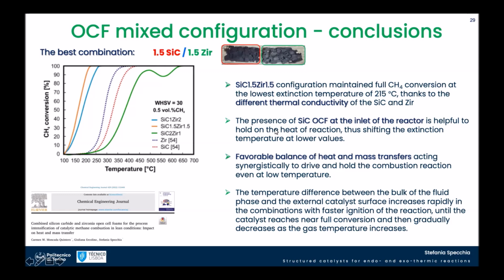The heat and mass transfer were very much enhanced compared to the single ones, and this is basically because we were able to use the little heat coming from burning the first molecules, which are being oxidized at low temperature, to provide that heat to speed up the reaction of the following ones, and to really speed up the reaction a lot, and then perform the full conversion of the methane at very low temperature.